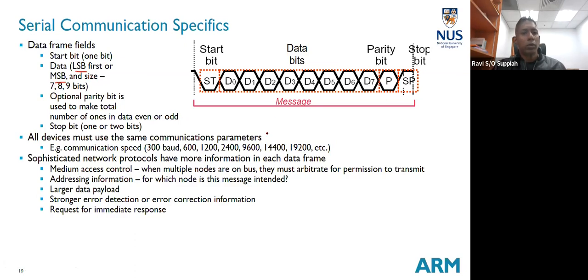Okay, most microcontrollers have varied configurations, LS bit or MS bit. I think Arduino Uno also has that. Data size packet 7, 8, 9, these are all common configurations. Parity bit is again for error correction. You may use it, you may not use it. Baud rate, again, you have quite a few standard baud rates. Most devices by default should have a basic operation speed of 9600.